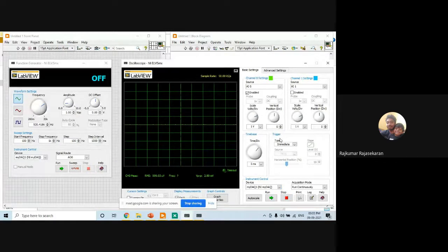Measurements can also be synchronized. Let's say you want to make measurements from one single cycle, half cycle, or something like that. You have some type of trigger available. You can say it's triggering. So I need to set the channel source.